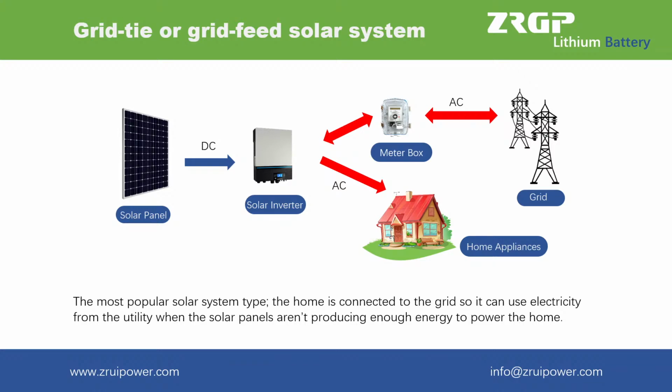On-grid solar systems are by far the most common and widely used by homes and businesses. These systems do not need batteries and use either solar inverters or microinverters and are connected to the public electricity grid. Any excess solar power that you generate is exported to the electricity grid, and you usually get paid feed-in tariffs or credits for the energy you export.